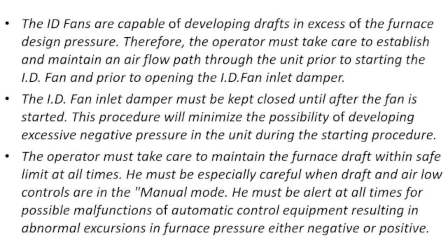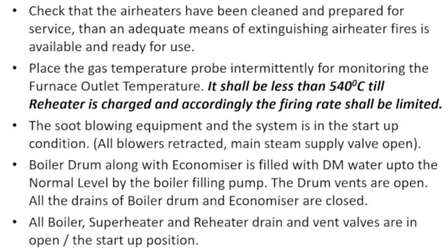The operator must take care to maintain the furnace draft within safe limits at all times. He must be especially careful when the draft and airflow controls are in the manual mode. He must be alert at all times for all possible malfunctions of automatic control equipment resulting in abnormal excursions in furnace pressure, either negative or positive.